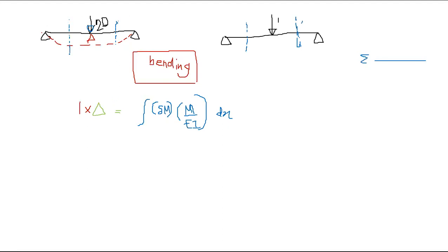So I'll write this part. I'll apply a clockwise moment, right? Once you apply a clockwise moment, you know there's a reaction of 10. So you can write the moment equilibrium of this portion above this point. So M plus, let's say this distance is X measured from the left end, where X equals 0. So M is minus 10X.